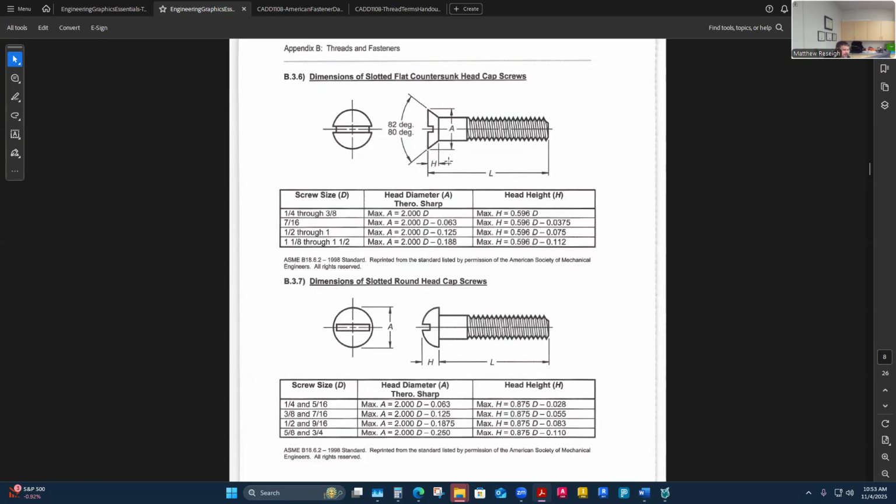So when someone has to cut that to sink that head into the surface, they have to cut that degree pretty accurately so that the entire surface of the bolt mates with the mating surface. I wouldn't want there to be some voided gap, like somebody did a 60-degree included angle and then I put an 82-degree head in there. I don't have the relationship that I need, where the angled surface of that fastener wants to sit.